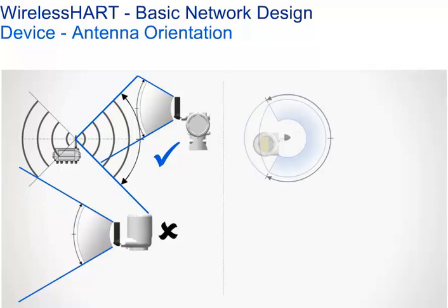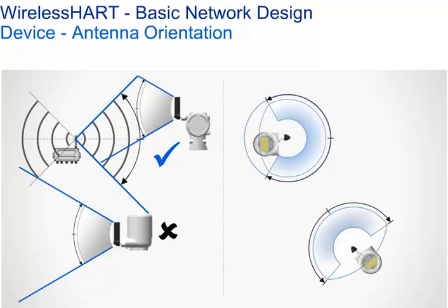This is less critical in the horizontal plane, but remember, to get the best communication link, antennas should face the direction in which the closest device is placed. This is to be considered in case any obstacles block other links.